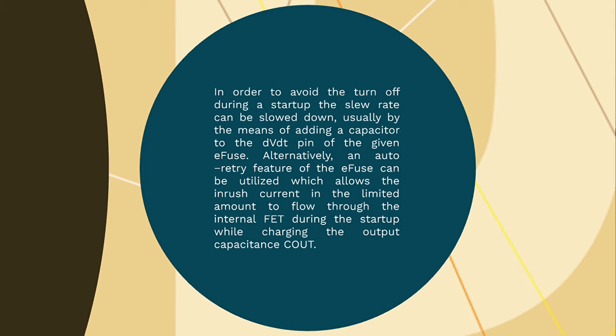Alternatively, an auto-retry feature of the eFuse can be utilized, which allows the in-rush current in a limited amount to flow through the internal FET during the startup while charging the output capacitance Cout.